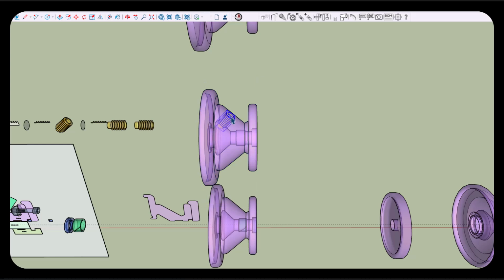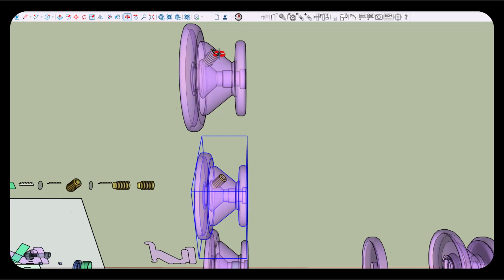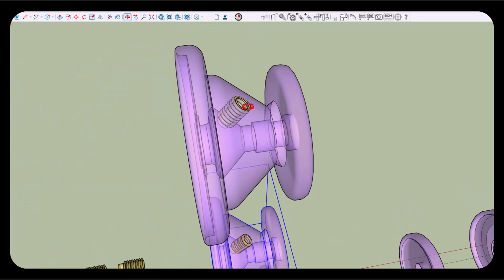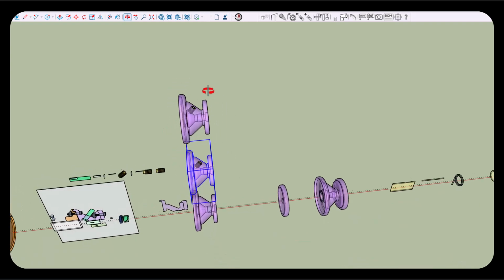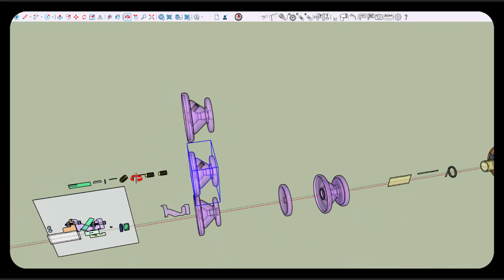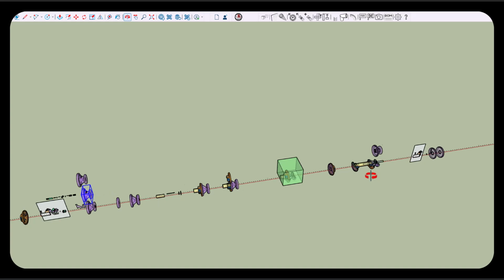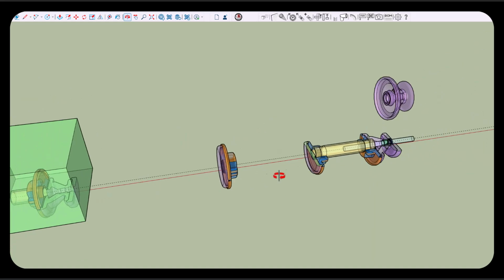This is a group, and this is a group, and I took this group and subtracted it from that group. And when you do that, you wind up with this. This is a 1/8 inch national pipe thread, and the purpose of this is to get the hydraulic fluid in. There's going to be another one of these 1/8 inch national pipe thread fittings on this end, so that you can put fluid into that end of the hydraulic cylinder.